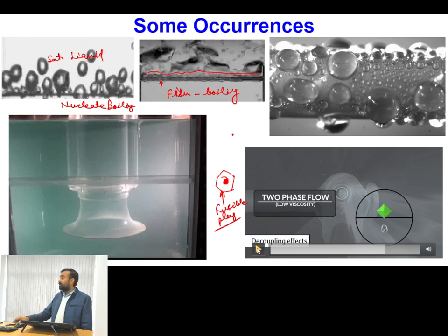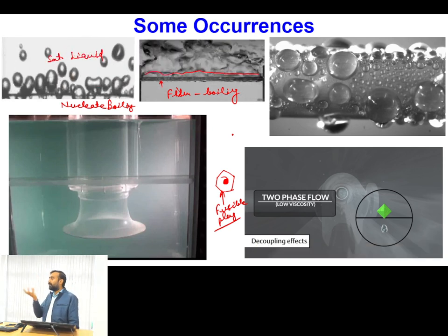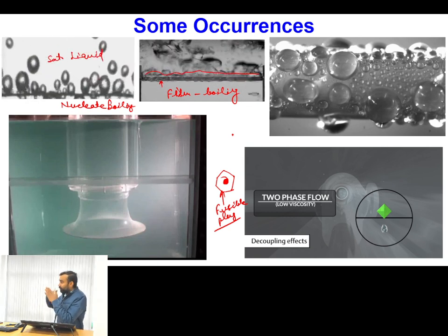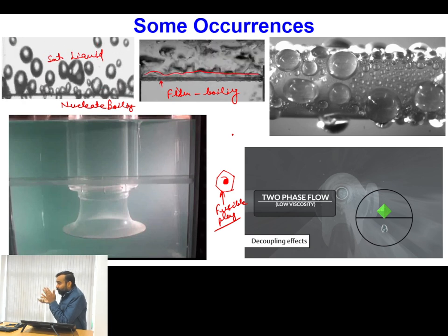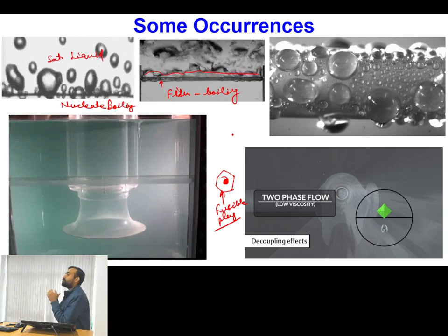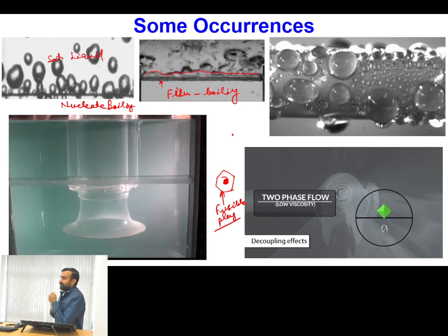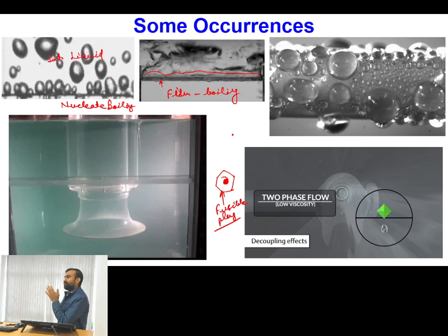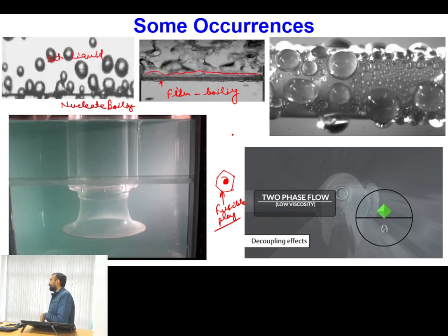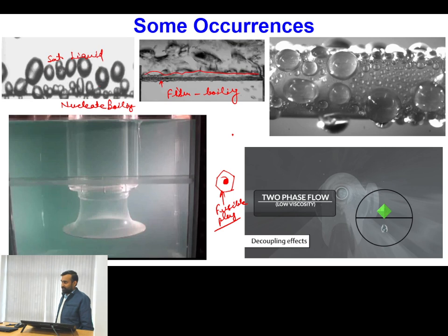Basically, the transducer outside is only measuring the tube oscillations, and the tube oscillation should match with the oscillations of the centroid of the fluid, then only our reading will be accurate. If there is a significant difference between the center of the tube and the center of gravity of the fluid at the cross section, then we will have error in our measurements.